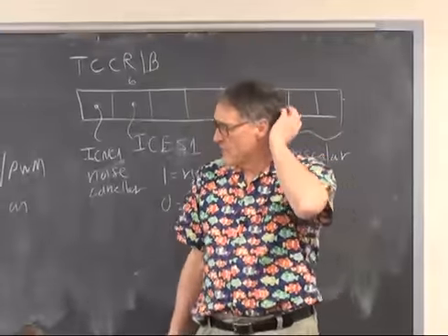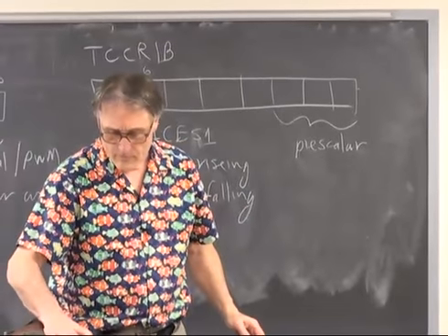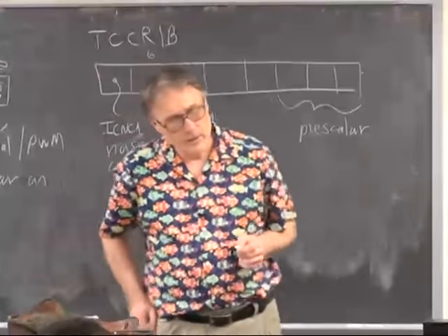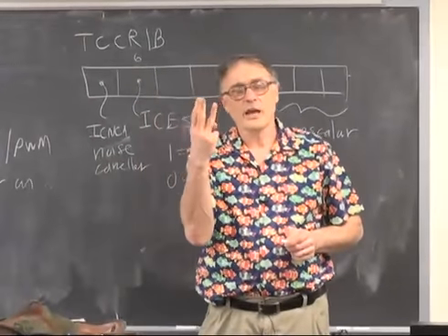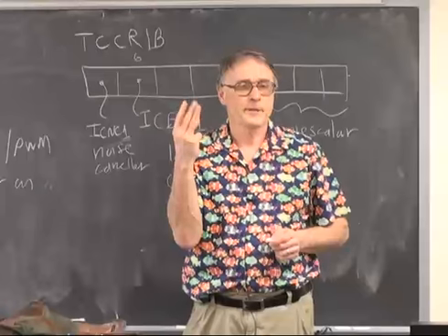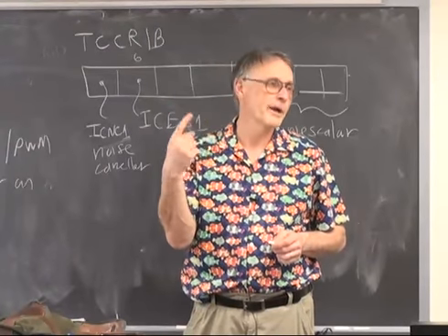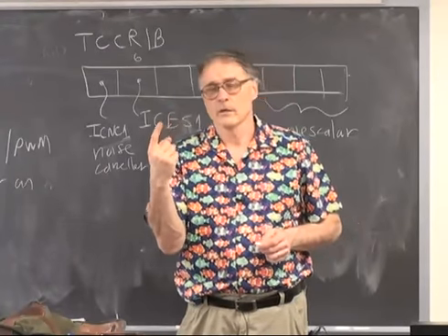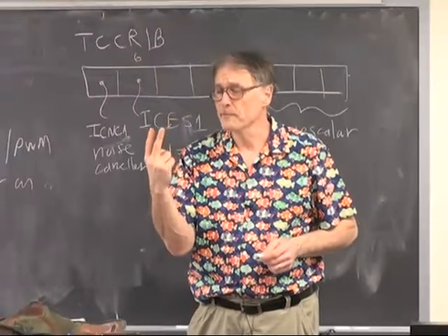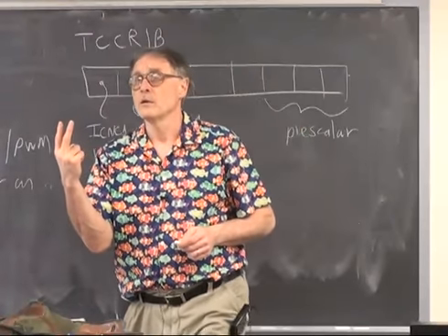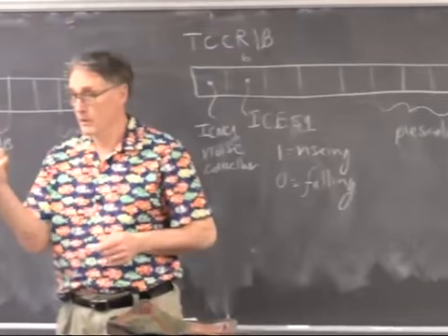So the example from Lab 1, do I really want to start? I'll start a little bit of this now. The example from Lab 1 then uses 3 timers in 3 different ways. Timer 0 is set up as a millisecond timer, boring, been doing that now for a week. Timer 1 is set up to capture the period of an incoming waveform, square wave.